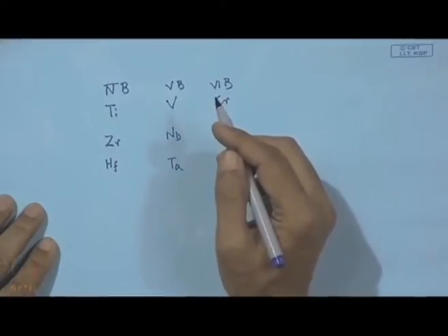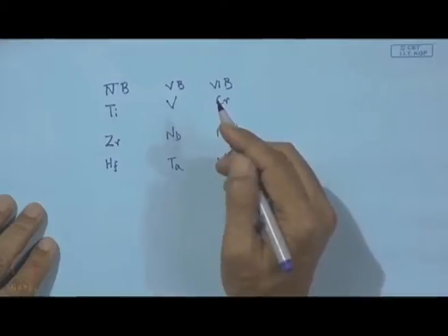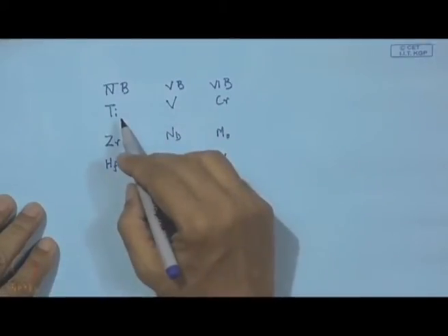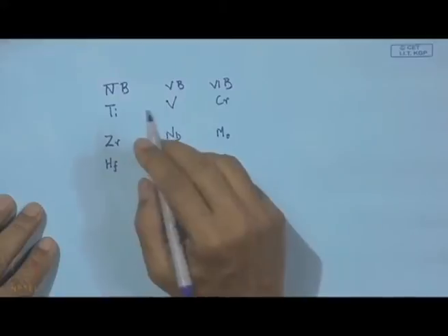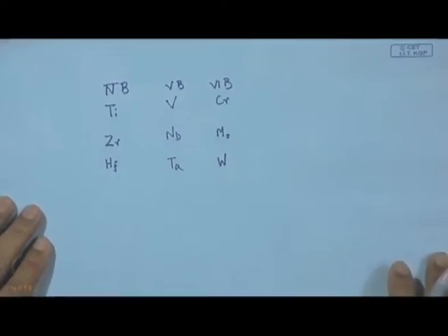Now, these transition elements are known as very good oxide formers, carbide formers, boride formers and nitride formers. So, these are the strategic elements which can be used as a solute to make the parent metal or parent alloy, which is otherwise passive towards the ceramic surface, activated.